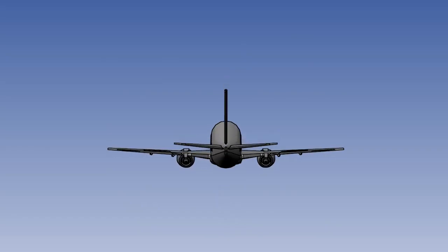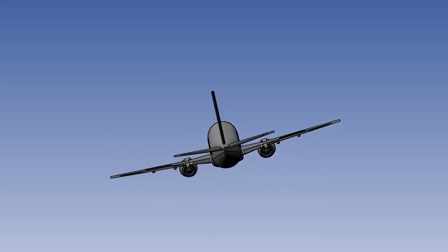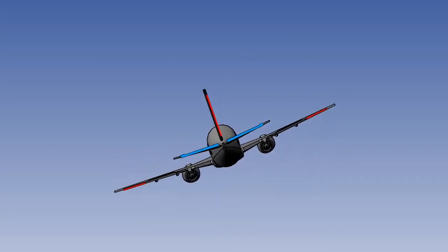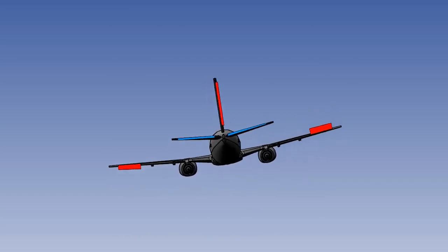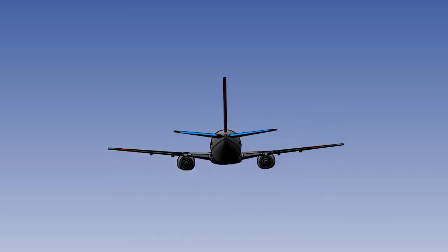Taken with the aforementioned restrictions on the use of the ailerons, these factors would suggest that the ailerons and rudder should be kept neutral until the wings are unstalled, and only used when the aircraft has reached a safe speed margin above the stall.